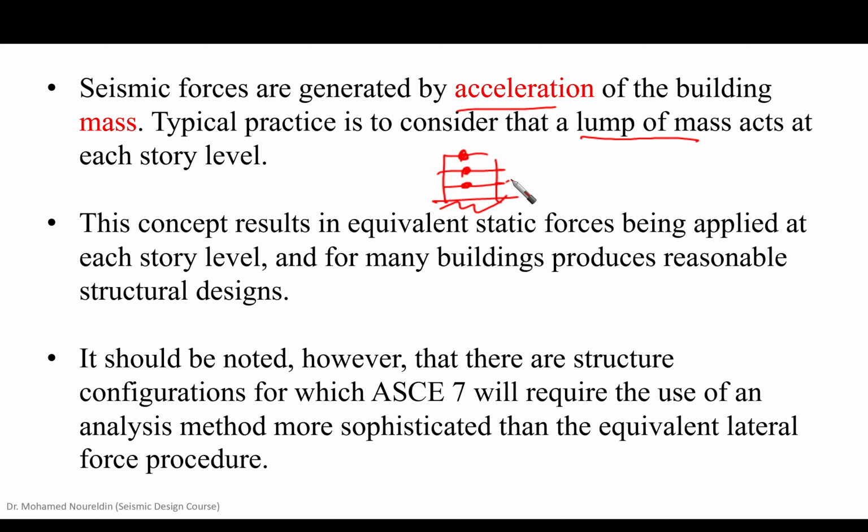But we are going to use our equivalent static force method to say that force is going to be applied on the structure relative also to the masses here. This concept results in equivalent static forces being applied at each story level, and for many buildings produces reasonable structural designs. And this is an important issue. For many buildings it produces reasonable structural designs.